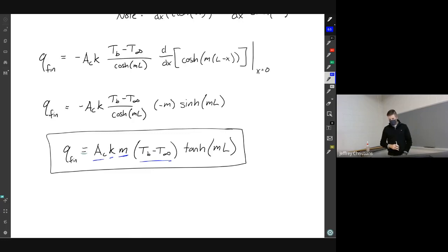So how would you improve convection? Well, you could make it higher thermal conductivity. That's why systems with fins are typically aluminum, because aluminum has a thermal conductivity of 180, which is fairly large. You could go to copper. Copper has a thermal conductivity of like 400, so you could double how much heat you're dissipating by going from aluminum to copper, but copper is a lot more expensive. But knowing that, you have this value for k, how this works.